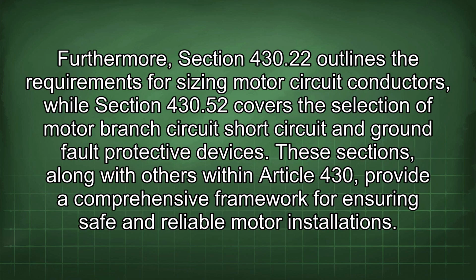Furthermore, Section 430.22 outlines the requirements for sizing motor circuit conductors, while Section 430.52 covers the selection of motor branch circuit short circuit and ground fault protective devices.